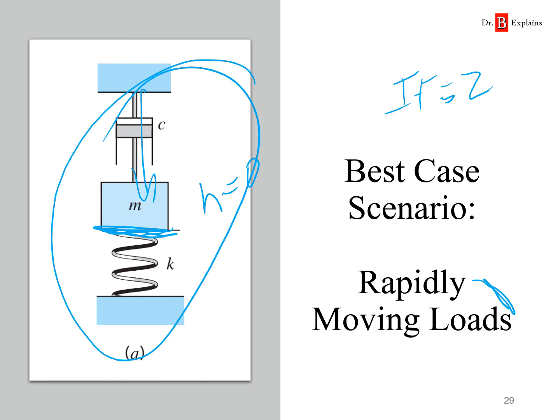The book doesn't provide an answer. It's got to be between 1 and 2. So my advice for you is, if you're worried about impact, but it's not a direct impact, if you go with an impact factor of 2, that means if you design for double the load or double the deflection, then you're overkill, because this is not even accounting for something that is slowing down. So just use at least an impact factor of 2 and you'll be fine.